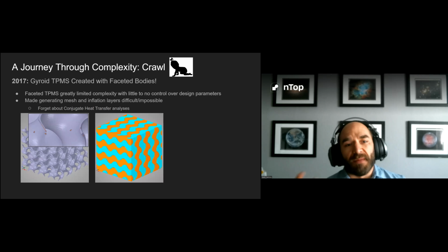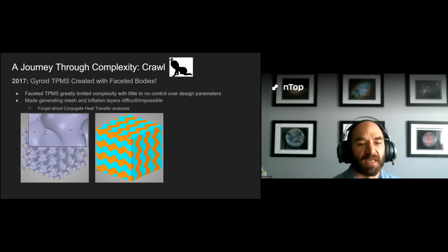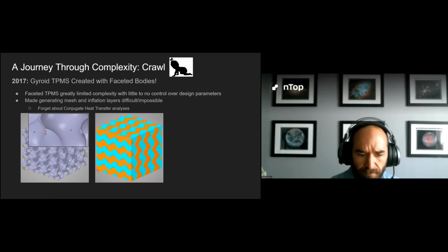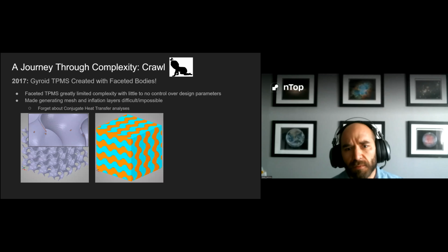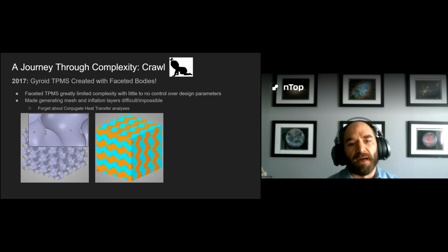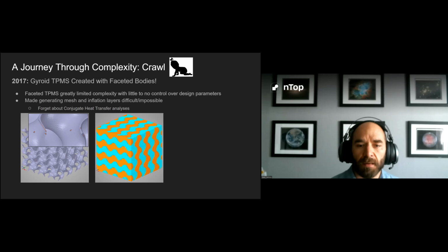This made generating meshes and inflation layers either difficult or sometimes impossible because the fluid domains captured the faceted geometry of the solid that we see on the left. We tried to push this through traditional CFD tools, ANSYS CFX, ANSYS Fluent at the time, and we just couldn't find a mechanism to do that.